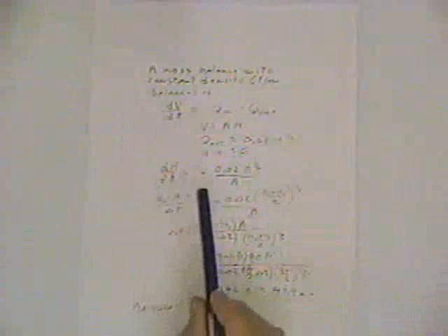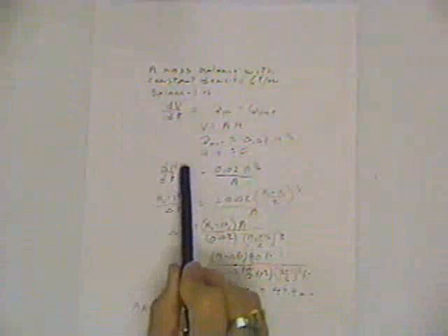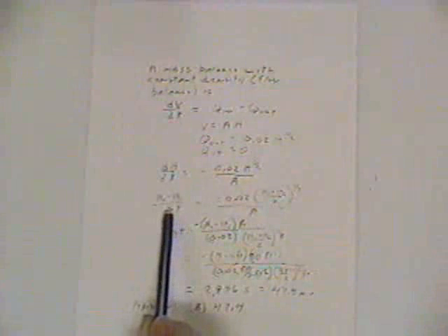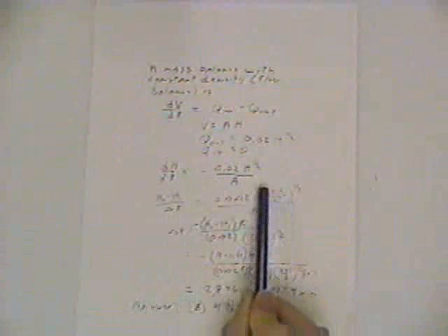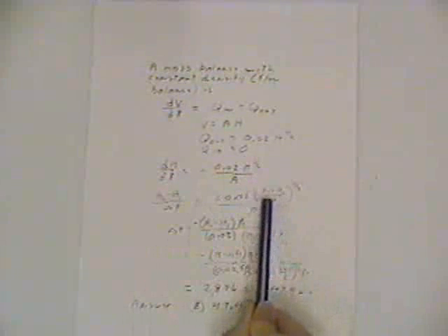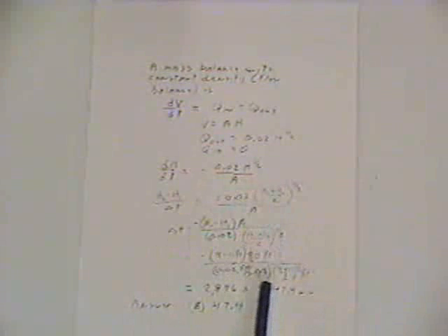What the problem specified was to apply a finite difference approximation to that problem. The way it was set up, it is easier to do this problem in a Euler-like method, but not in a direct Euler method. So what is done is to estimate the derivative as the change in h between any two heights over delta t, and then use an estimate for the h on the right-hand side, which is the average of those two. This is saying that whatever delta t we're concerned with, it will result in some change in the height. We'll use that average height to estimate what the flow going out is.